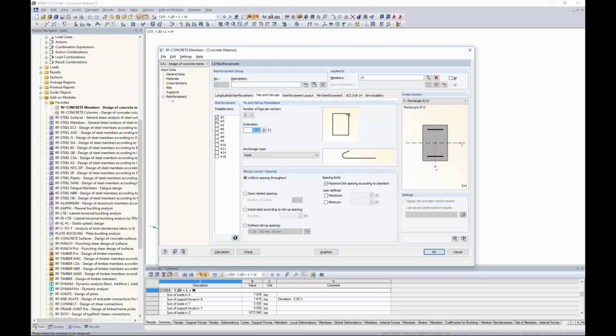It also tells us in the commentary, and this is just common sense, that if you have shear cracks that are approximately the same angle as your shear reinforcement, well, your shear reinforcement is basically non-existent at that point. So that's just something to consider when you are putting in some type of angle other than 90 degrees here.